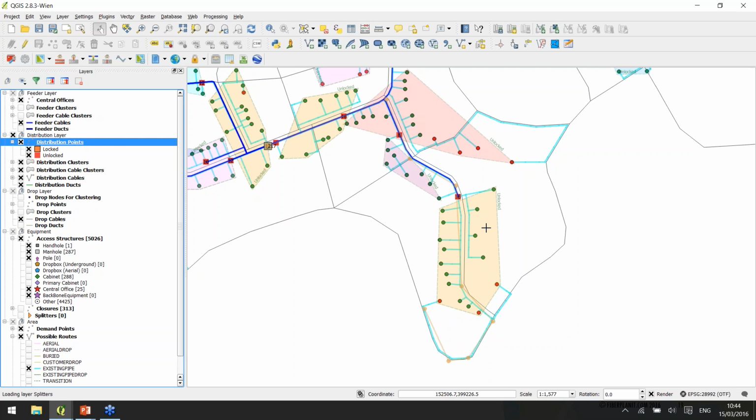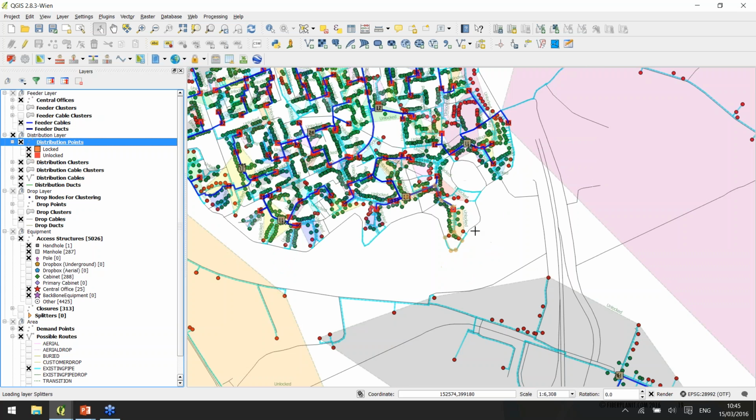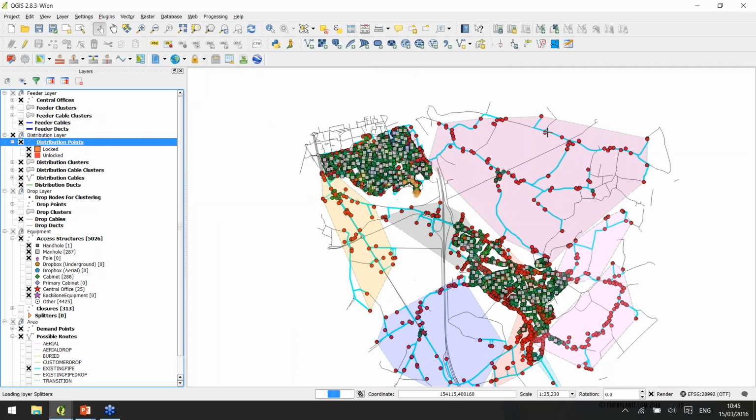So when doing this design, you can still evaluate what the minimum amount of homes should be to have a certain percentage of homes within reach of the 100 meter. So the FiberPlanIT can help you in making this decision and determining where in the end new cabinets should be placed and how they can be served. And this can be done, again, for a complete area at once.